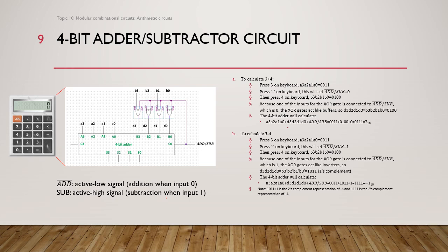And we have some XOR gates, and in this 4-bit adder, we have the data A and data B, that's the data input, and we have a control input, which is connected to the carry in C0. For output, we have the carry out, which is C3 here, and we have the sum output S3 to S0.